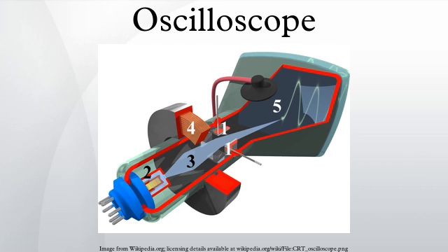Other features: some oscilloscopes have cursors, which are lines that can be moved about the screen to measure the time interval between two points, or the difference between two voltages. A few older oscilloscopes simply brighten the trace at movable locations.